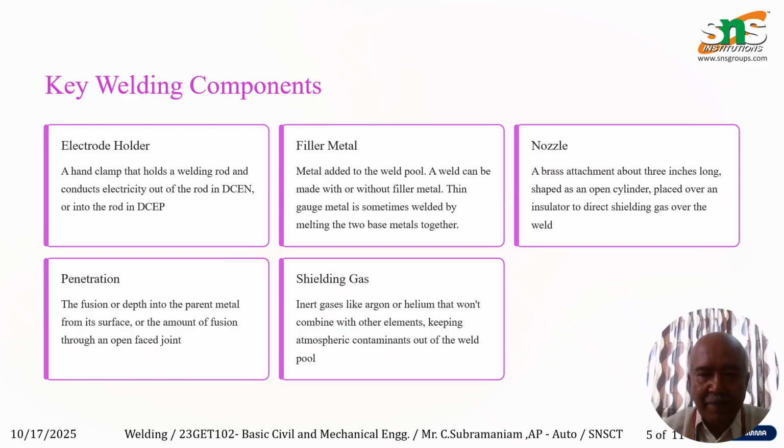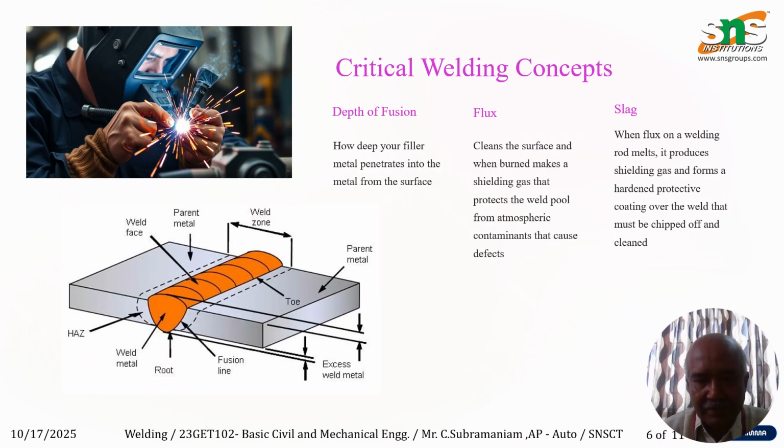These weldings will have penetration. The penetration is the depth of fusion into the parent material, such that the heat will be penetrated. And either in gas welding or in arc welding, the shielding gas will be provided, such that it will not have direct contact with the atmosphere.